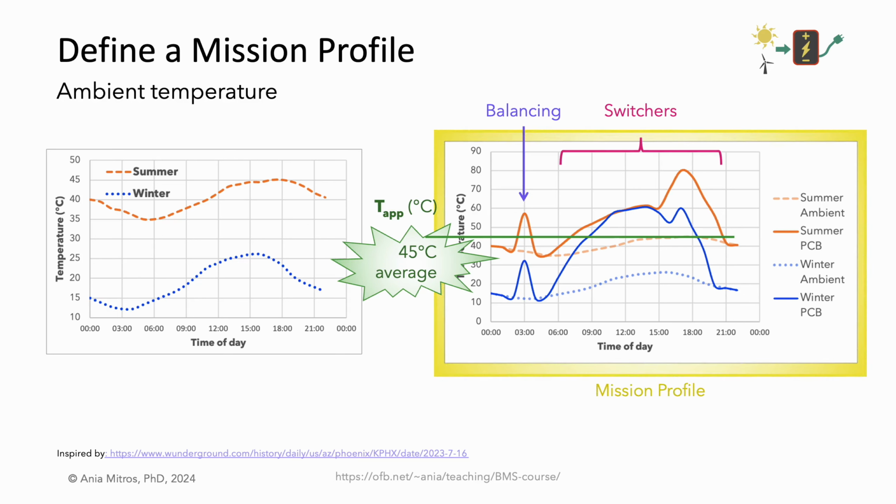This temperature over time profile constitutes the mission profile needed for designing our reliability tests. In reality, we would also include the maximum operating voltages, since some failure mechanisms are exacerbated by increased voltage.